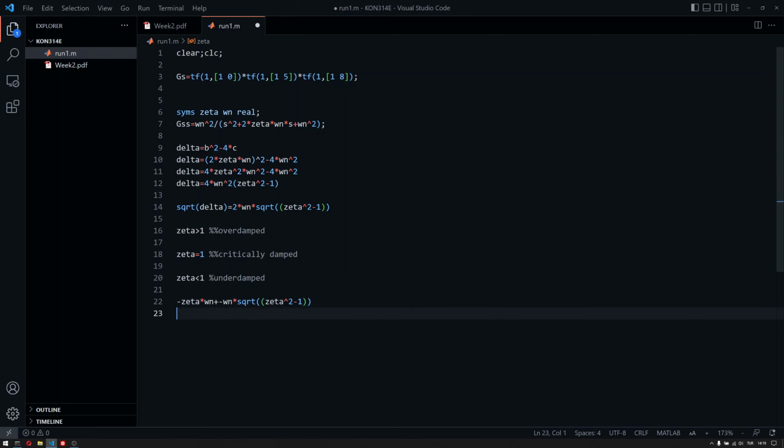So that's that. Therefore, if we want to set the settling time equal to 4, for example, zeta times omega n should be equal to 1. That's one piece of information that we gathered now. But if we have a second order system, this settling time will be useful. But if we have a higher order system, then we are in trouble, actually. But no problem, we'll talk about that.